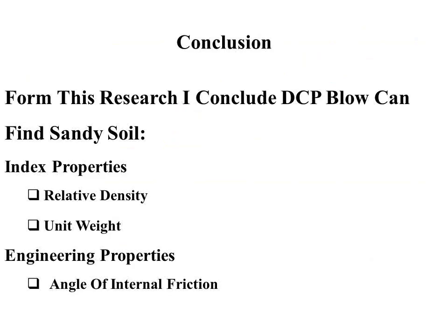From that research, I conclude the dynamic cone penetration blow can find a sandy soil's index properties, that is relative density and unit weight, and also find the engineering property, that is the angle of internal friction.